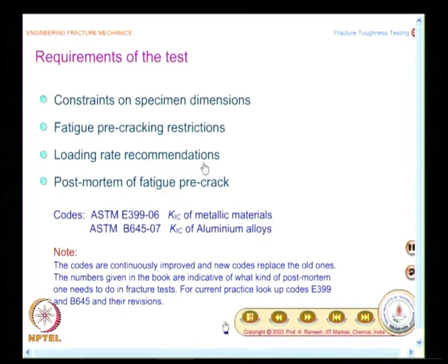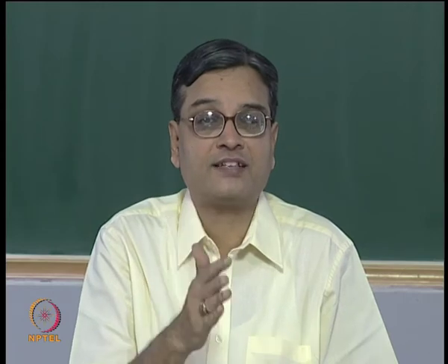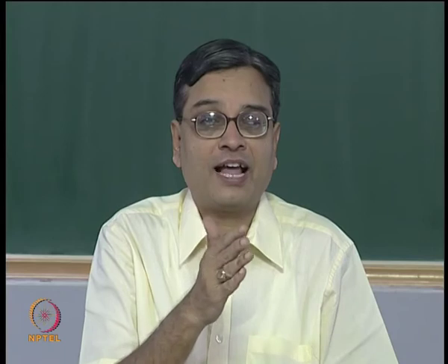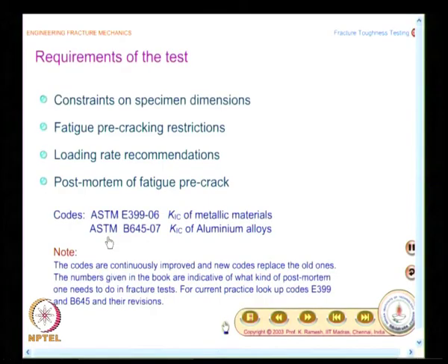After all this, you have to do post mortem of fatigue pre crack, because that is going to decide whether the crack was in the way it should be for you to accept the test. So, at this stage, if the crack is not all right, then you have to scrap the test, then you have to redo the test, and you have standards for that.